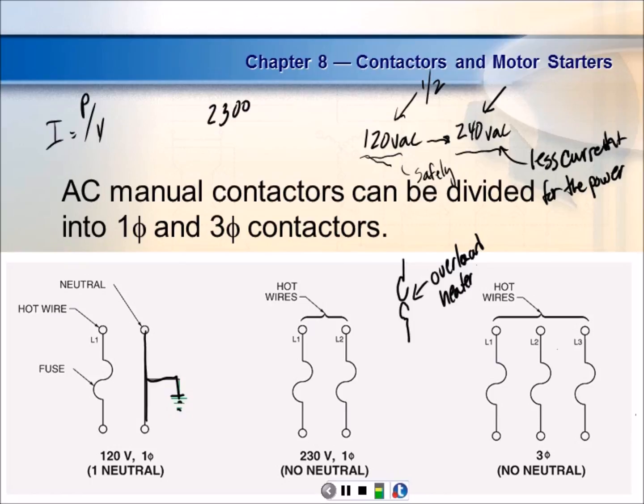So that's why, if you got a circuit breaker panel in your house, you look at the low voltage breakers, there's only one of them, right? You look at the high voltage breakers, there's two of them. Now they're ganged together. Okay, y'all understand? They're ganged together, and why do they have to do it? Because both sides are hot. Everybody understand that? And then, of course, three phases, all of them hot relative to each other. So with three phases, we would have to put an overcurrent protection device or a fuse in all three phases.